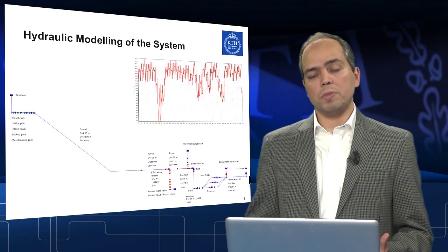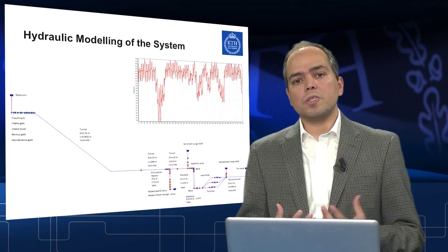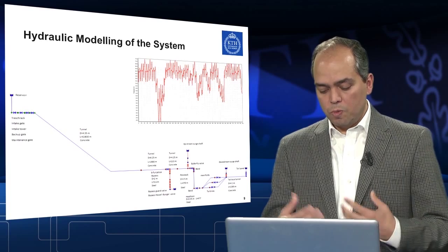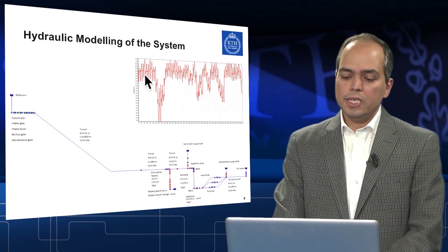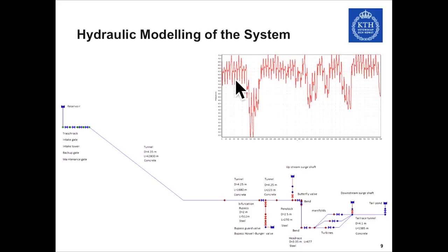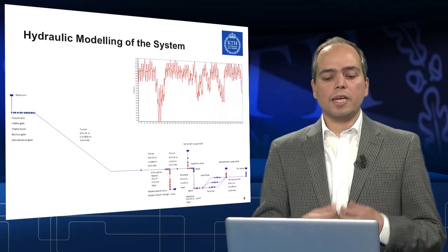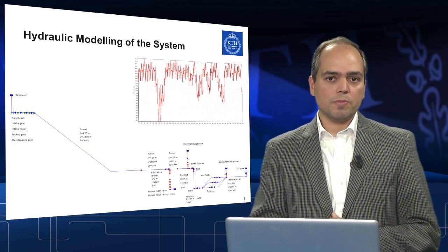And how this system could be calculated, and of course there are computer model programs in order to model the hydraulics within the system. So what I wanted to highlight here is that, for example, this one shows the results of that program, the available head during the different times. So depending on, let's say, the reservoir management and the flows that are released, the available pressure is also different on turbines. So nowadays, these types of modeling and hydraulic calculations are used for larger scale projects.